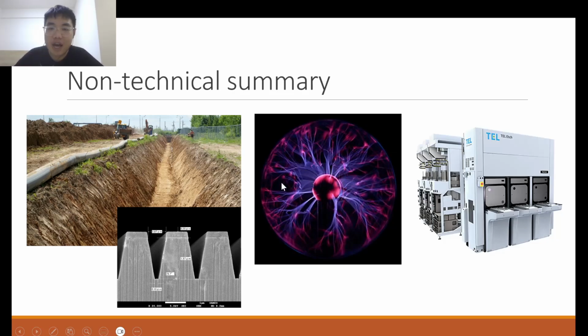And so in dry etch, the main etching environment is that of a plasma. So this is different from wet etch, where the environment was an aqueous solution. So now in this case, we have a low pressure gaseous plasma that can consist of different kinds of gases. Okay, and so to achieve this environment and this etching, there exist specialized machines, right, dry etch machines, sold by vendors such as Tokyo Electron, among other companies such as Lam Research and so on.